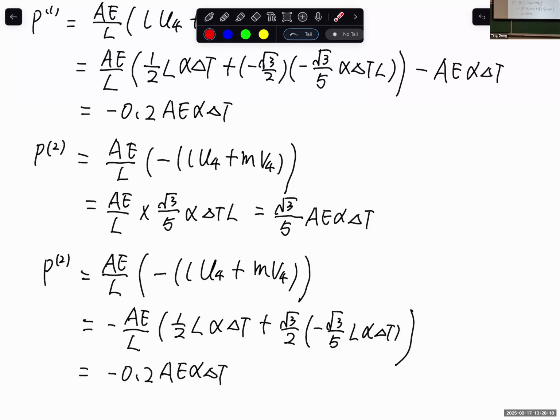And in terms of sign, the element force is always the same sign as the second node, right? So if I want to generate tension, at node J it goes in the positive x. So positive internal force, positive at node J, but at node I it is negative because it points towards the negative x direction.